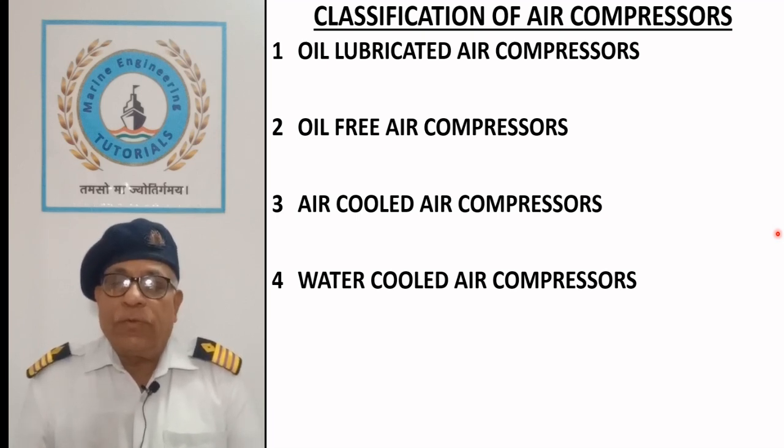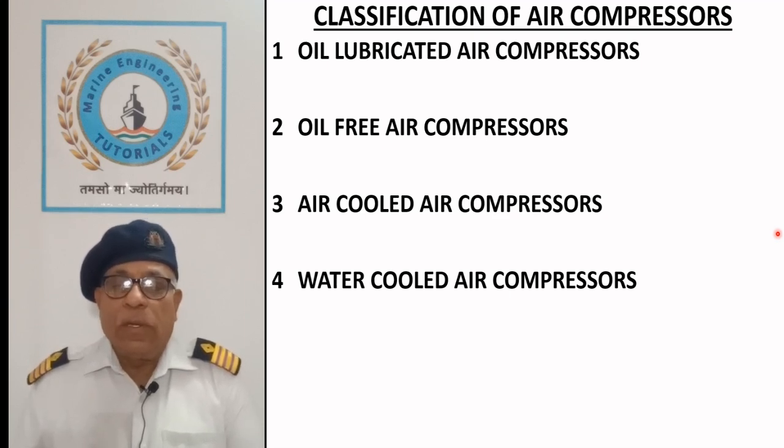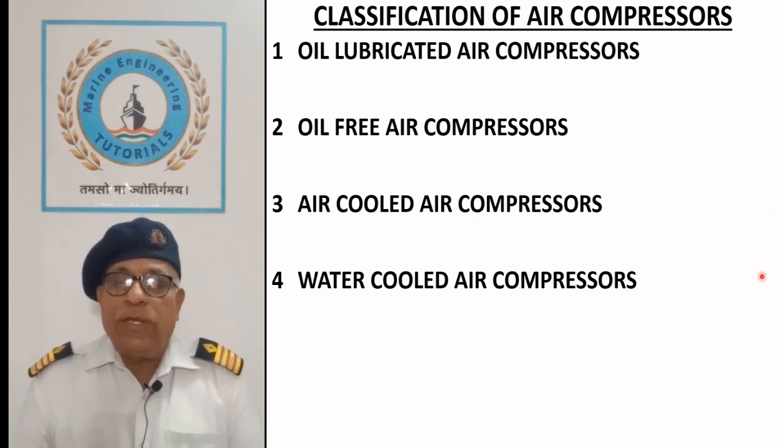Earlier compressors were cooled by seawater which maintained low temperature but caused more fouling on the water side. Nowadays, fresh water is used for cooling the compressor jacket, cylinder head and cooling the air between stages. Fresh water is treated to maintain alkalinity and prevent corrosion.